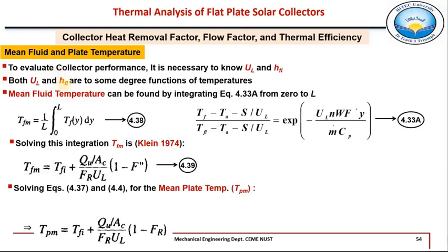Because to calculate this convective heat transfer coefficient, we need to evaluate the fluid properties, and those fluid properties need to be evaluated at the mean fluid temperature, that is the temperature of the fluid flowing through this solar collector.